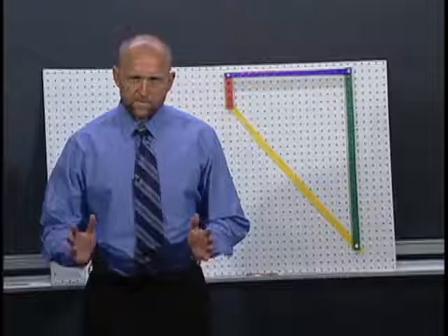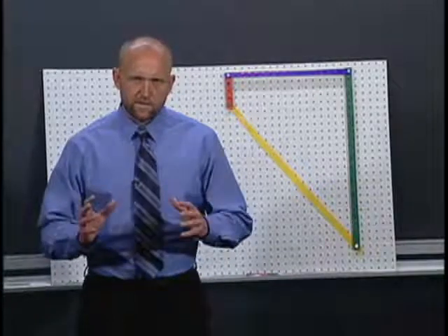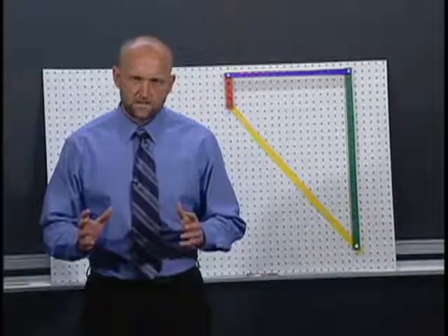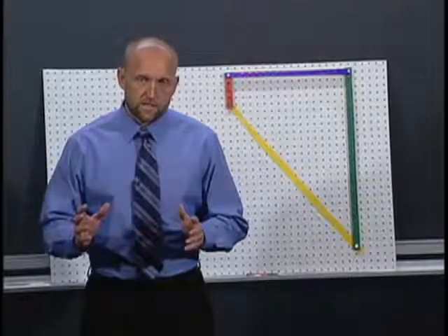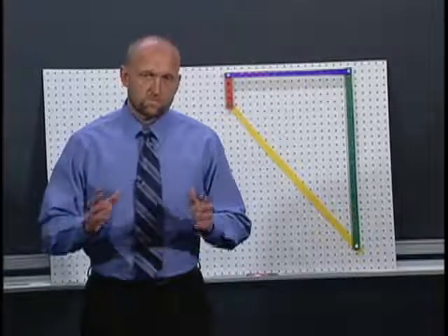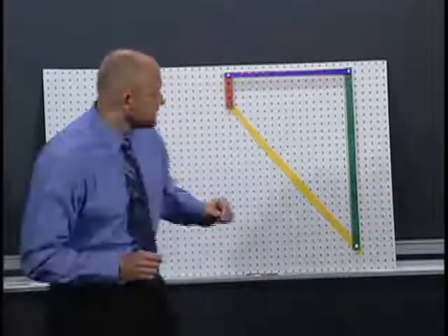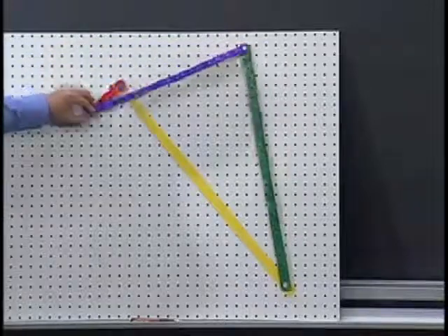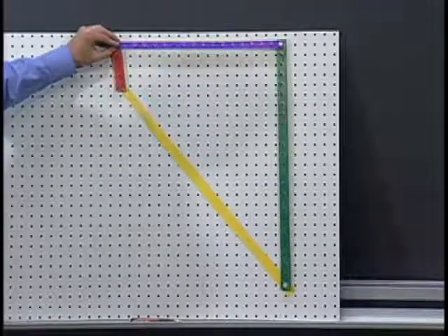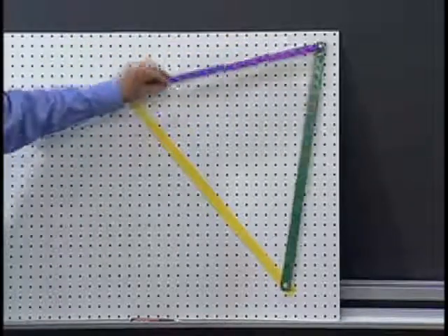Great, so you're back from that interactive work session, and you and the other students in the room and your instructor have been building actual physical prototypes that show how mechanisms work. And what you've seen is that one of the things you can do is make a 4-bar mechanism that converts rotary motion into essentially oscillating motion. What we have here is the red link. If it goes around and around, the farthest end of the green link essentially just goes back and forth.